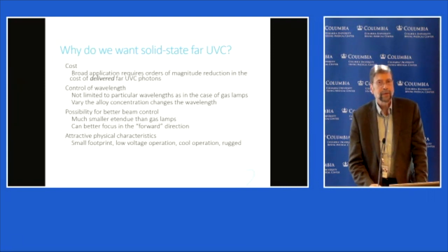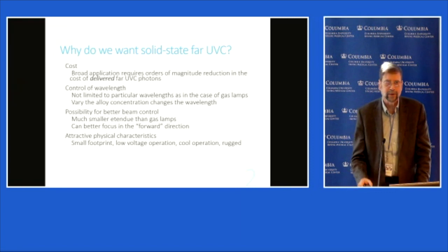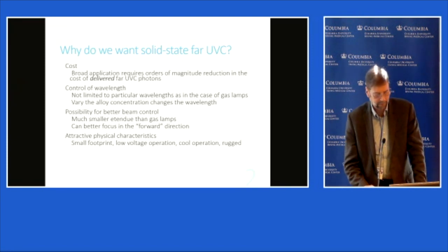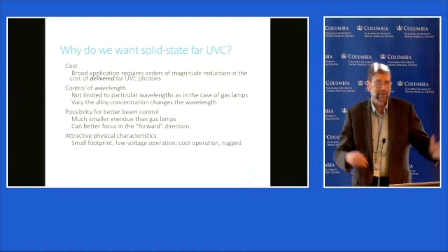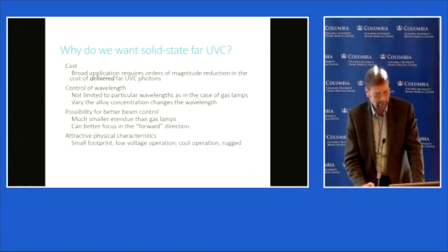We want to control the wavelength, and I think solid state devices will let us control wavelength better. Instead of being stuck with what nature gives us, we can vary the alloy concentration in these compound semiconductors and change the wavelength that way. There's the possibility for better beam control. Michael Kneisel talked a little bit about that, but it's possible to get a much smaller étendue. It's a technical term, but it just means you can steer the photons, so you can send them to an optical system and focus them where you want them.